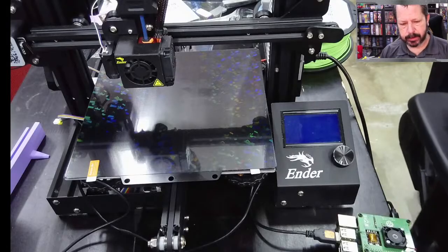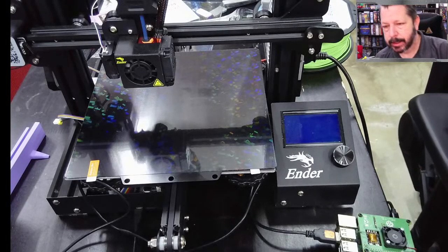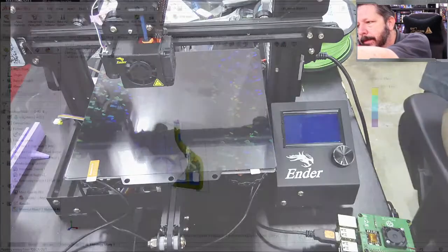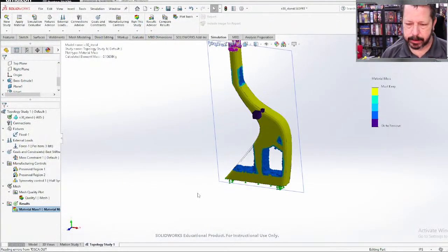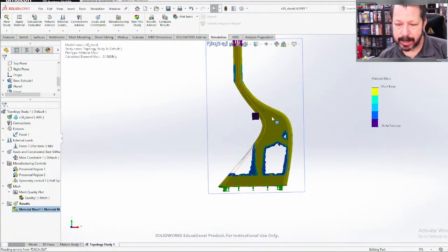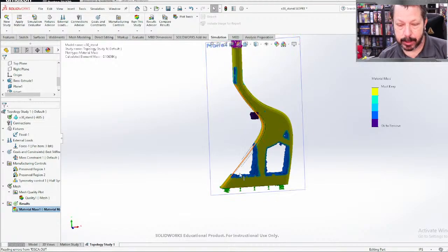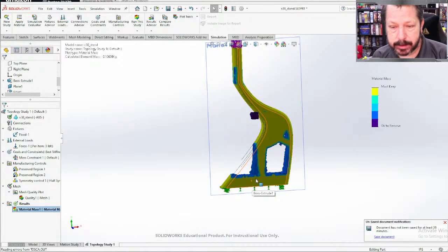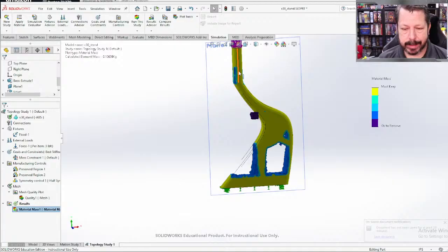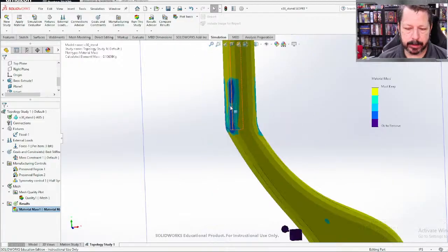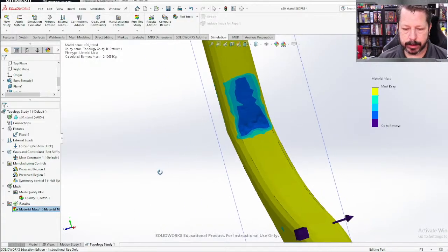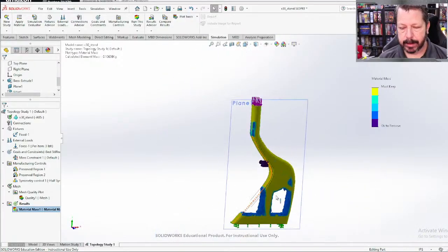Oh, we've got some results. They're not very exciting, but we do have results. All right, this is what you end up with. It says that I really can't remove much here. I made it too thin, but you can do a little bit down in here, so I can basically chop off that corner. It only kept this part down here probably because I told it to preserve the region. Same thing up here. It did say you could probably get rid of a little bit here, although that doesn't seem worth it to me. That doesn't really do anything.